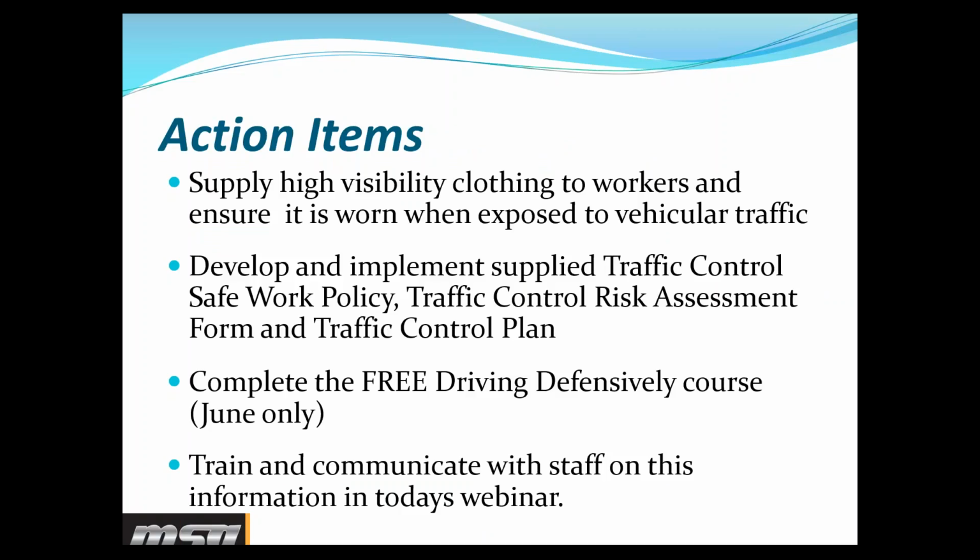So as we get to the tail end of our webinar today, I encourage you to take action and challenge yourself on these items, such as to ensure that supply of high visibility clothing to workers is available, and workers who are exposed to vehicular traffic have that equipment of high visibility clothing so that it's worn and available to them. To take advantage of the information I'm going to send to you after the webinar on the traffic control safe work policy, the traffic control risk assessment form, and the traffic control plan.